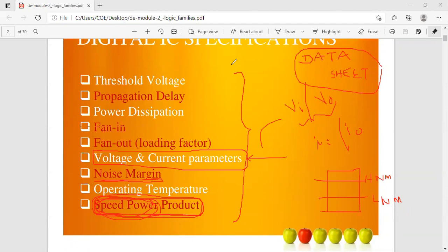For example, if I am going to select a simple transistor for my digital circuit, say an inverter, I have to refer to the input voltage level, the output voltage, and the maximum power withstanding. And one more thing you might have studied in electronic circuits: the peak inverse voltage value, voltage rating, current rating, the power dissipation level, and the temperature withstanding.